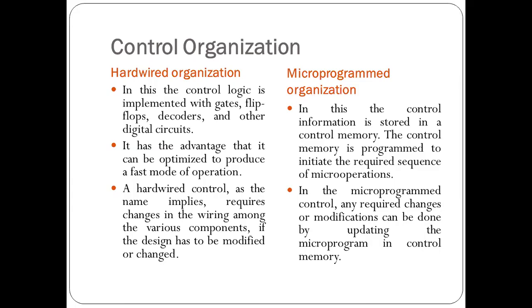These control signals are the inputs needed for a multiplexer for selecting one of the registers or the memory, which places the data onto the common bus, or the controls for the registers like load, clear, and increment, or the controls for the ALU to declare the operation to be performed on the accumulator along with the data register, or just the accumulator. These control signals will be generated by the control unit.